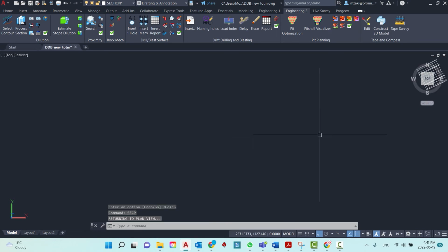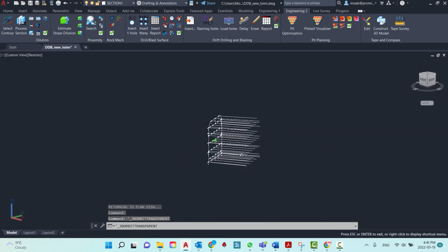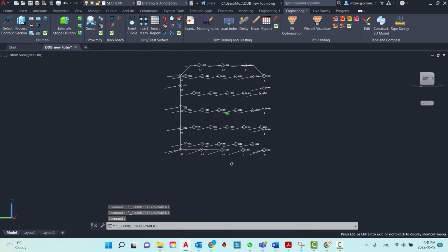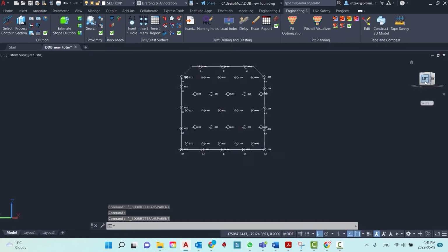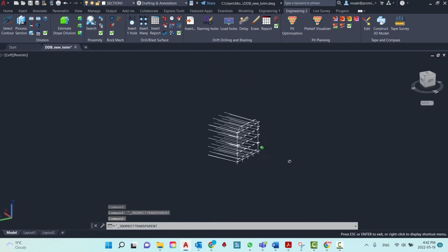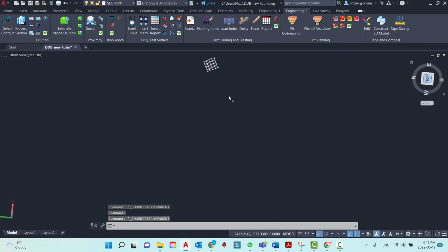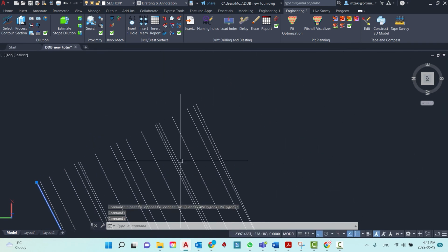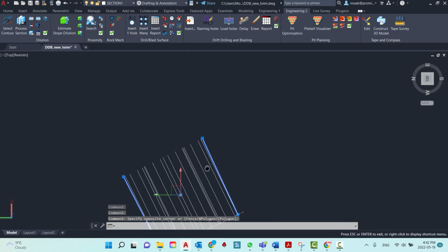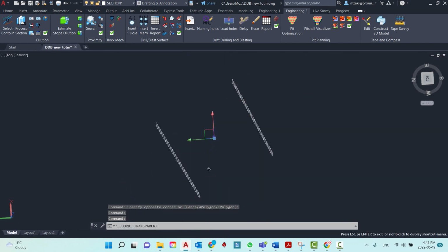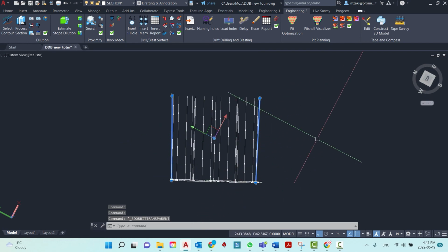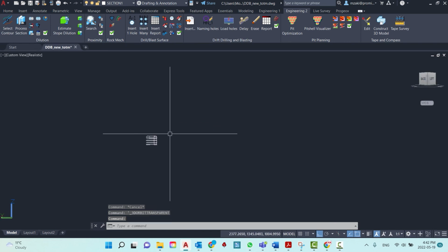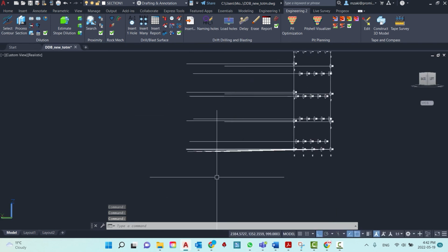If you go to plan view, we can see that we have our side holes here. So let's actually see how that looks. Here we have these ones here. We can actually observe them from the top as well. So you see that these are dipping a little bit to the left and these are dipping a little bit to the right. So this is when we apply the azimuth, right? It's these holes here. And of course the top and bottom holes are sloping 2% above and 2% down.